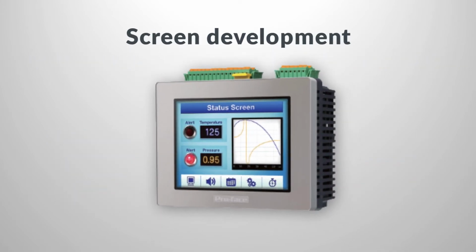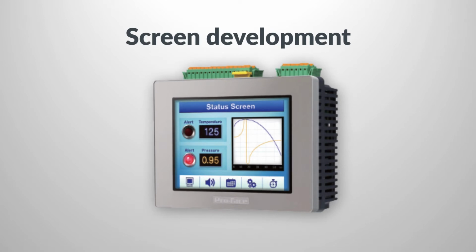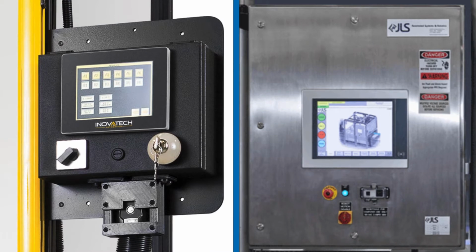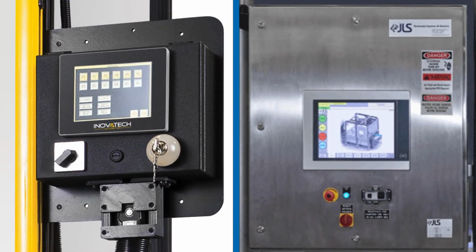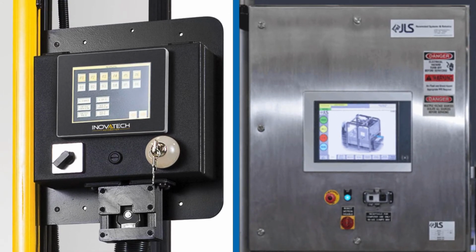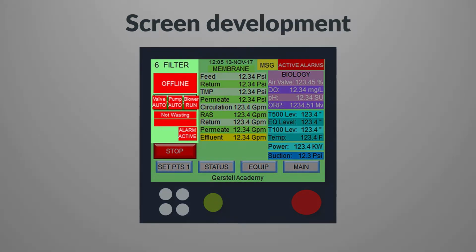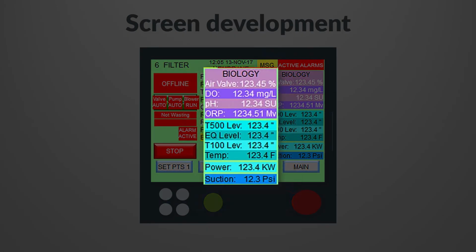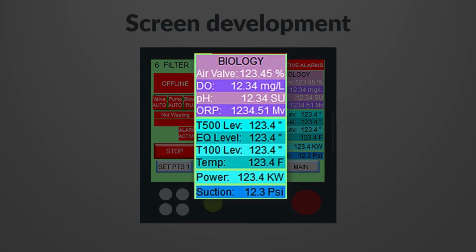When it comes to developing graphic screens, there are many basic HMI design techniques that should be followed, but an operator interface is more than just a pretty picture. That pretty picture may have too much information. Be sure to create logical zones on an HMI screen and limit these zones to 5 or 7. Create columns or put boxes around each zone and include clear, large text to identify it. Limiting the number of colors used and simplifying the navigation can also make for a better HMI.